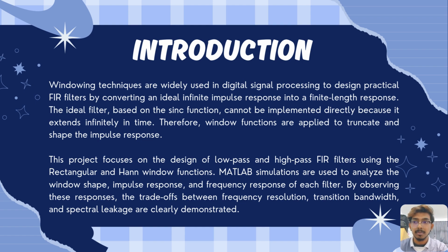The introduction part is about windowing techniques, which are widely used in digital signal processing to design practical FIR filters, which is known as finite impulse response filters, by converting an ideal infinite impulse response into a finite length response. The ideal filter based on the sinc function cannot be implemented directly because it extends infinitely in time. Therefore, window functions are applied to truncate and shape the impulse response.